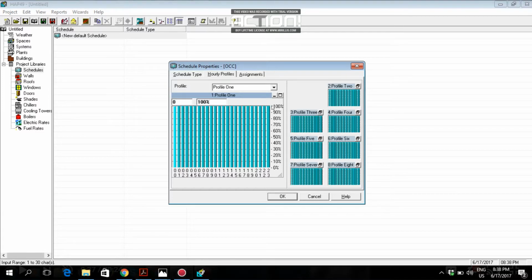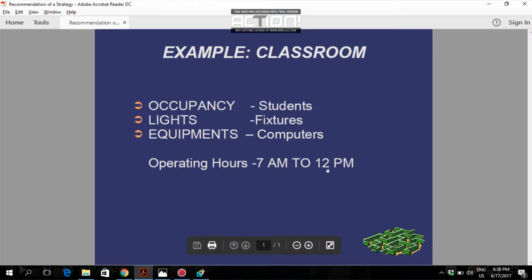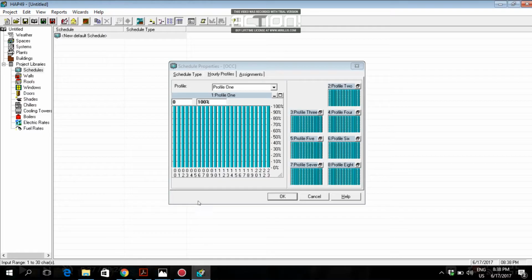as we agreed before in the last video, this classroom is going to operate for 5 hours from 7 to 12. Let me check. Yeah, operating hours 7 AM to 12 PM, 5 hours. So I will make a profile for 5 hours. From 12 AM there won't be any people present, so make it 0. If you click over here, like as I'm clicking, you can just reduce or increase this graph.